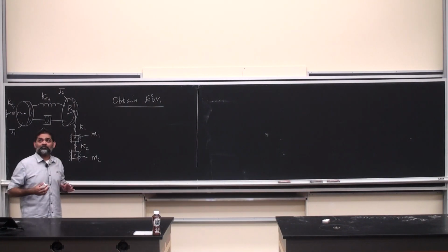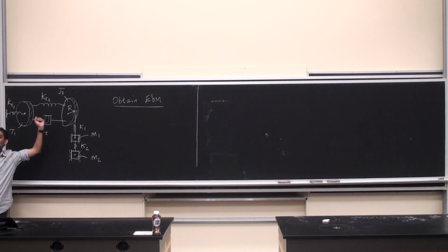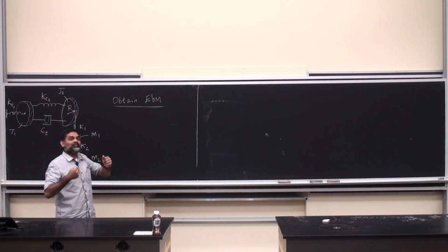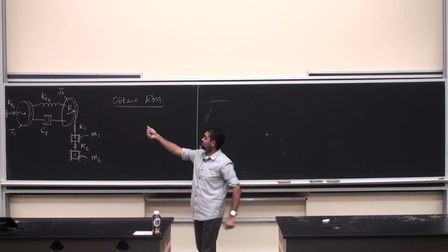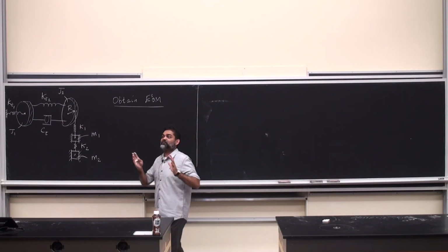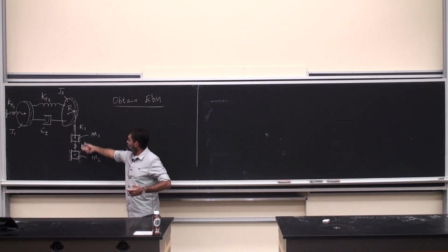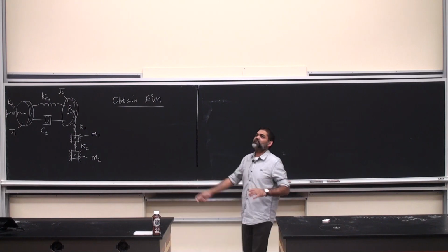One can say, for example, if I look at this problem, this reminds me of a pair of gears connected by a flexible shaft which is trying to raise a load by means of a string or some other connector elements. So the strings are modeled as springs. The flexible shaft between the gears is modeled as a set of torsional springs and dampers. The gears themselves are modeled as two inertial elements. And the loads that they're trying to lift are modeled by these two masses. So that's a physical example.